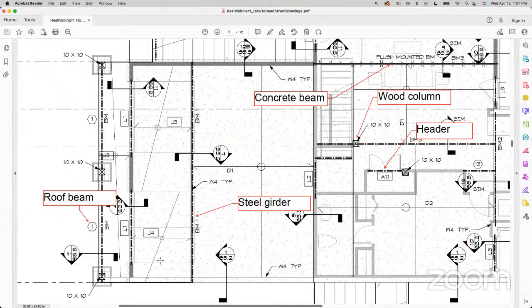Oh, and then it looks like another question here from Nabeen. Sorry, I missed this. So when you link that joist to the deck beam, will the software automatically link the joist beam spacing 16 inches? Yes. So when we're linking it as a line load, we are essentially estimating it as a line load using that 16 inches on center tributary width.